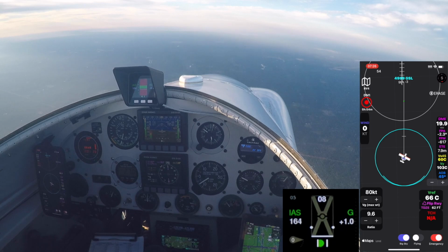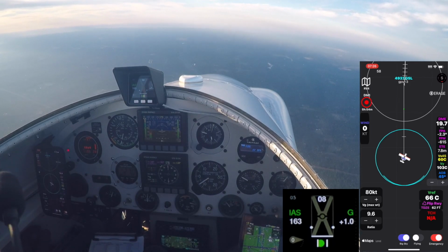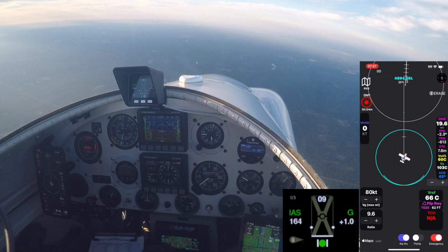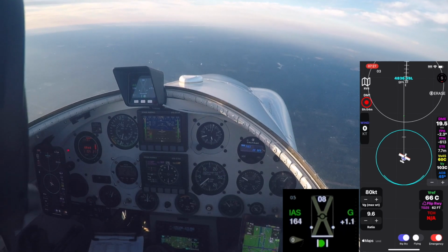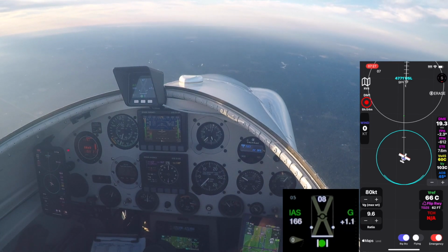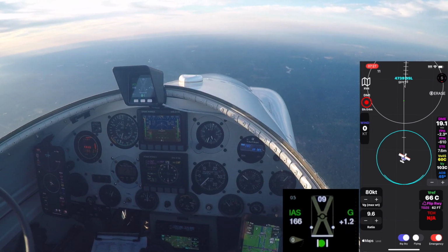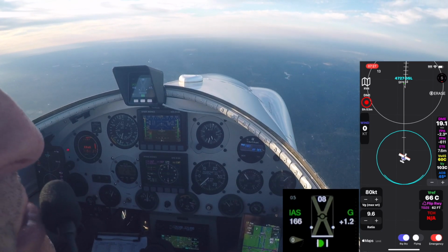So the feedback I get from the boom in the cockpit is I've got an LED on there, and by monitoring the LED, I know that I've got good data coming in from the boom. The camera also has a hot LED, so when I'm doing camera and boom checks, I'm just checking the LEDs to make sure that my test systems are working.